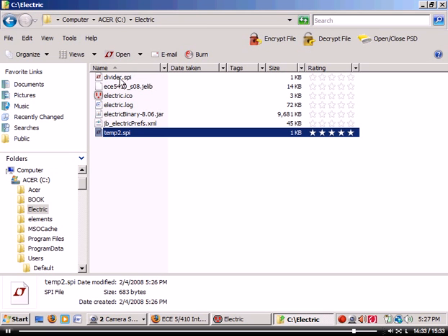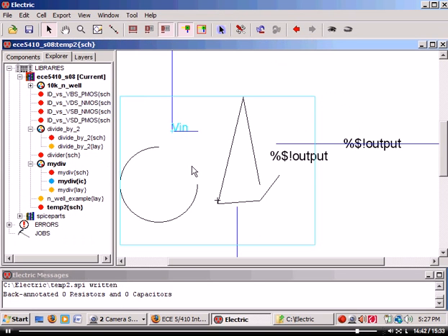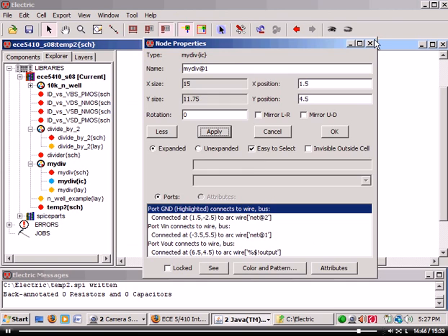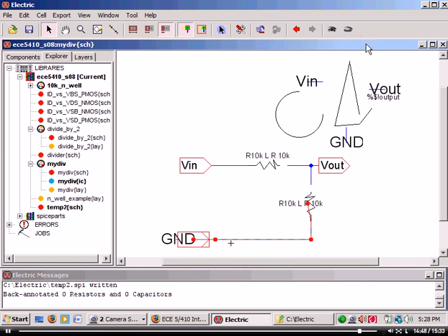Okay, good question. I'll remember to repeat it. The question was, if you have SPICE code within a schematic, like down in, let's just hit fit and do a Control D and go down here. Let's say you put SPICE code in here. It will place it in the sub-circuit. So it will look at it in the subcircuit, but it won't look at it in the higher ranking, in the main part of the cell.